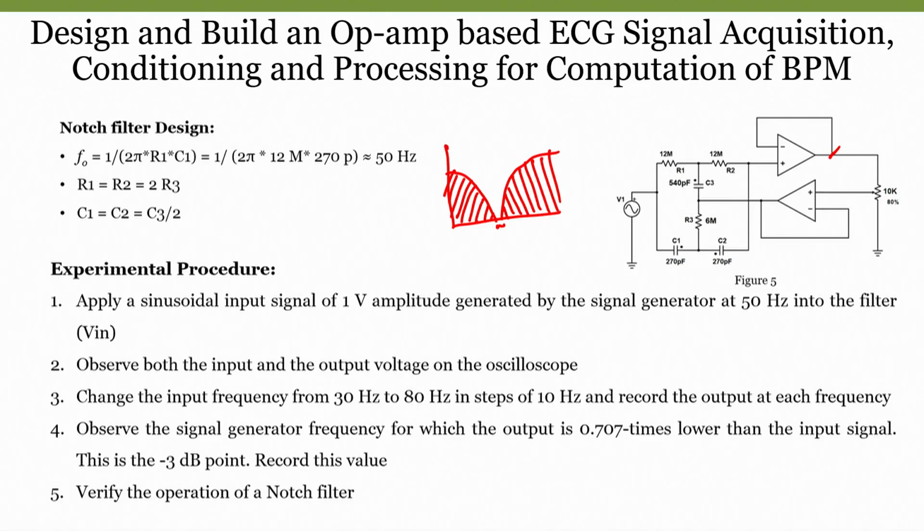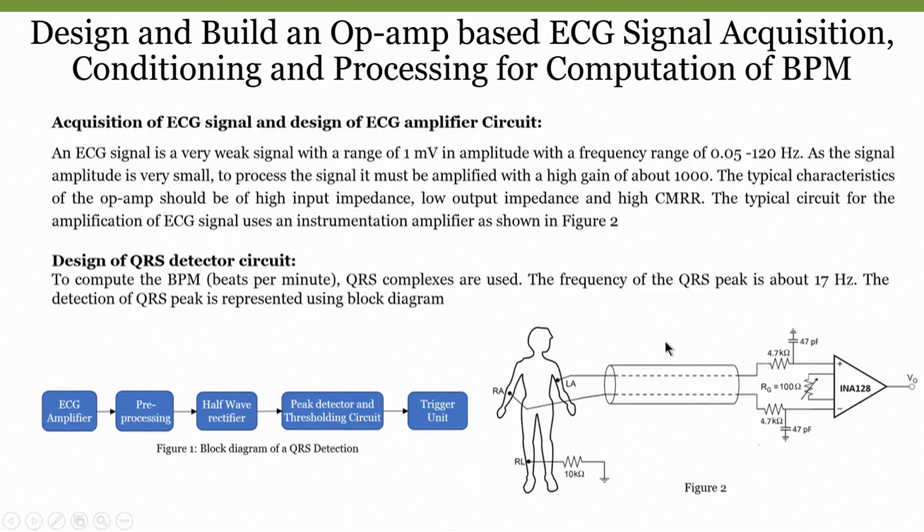Now, we will see the next step in our signal conditioning and processing unit. If we recall our block diagram, we will see the ECG amplification sometime later by the end of the experiment, and we have done the filtering part, which is nothing but a pre-processing part, which we require especially low pass filtering, high pass filtering, as well as notch filtering. Now, next step is what?